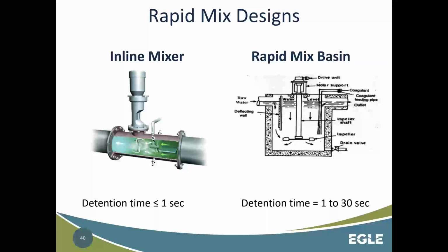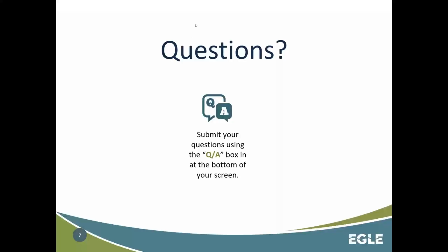Just want to repeat that when you get to flocculation, you're looking at gentle mixing. So we definitely don't want to mix the water rapidly to promote additional collisions. And then it looks like a few folks had adding additional coagulant. Typically, that's not a part of the flocculation process. So maybe just a little mixed up. Again, the terminology is important and they kind of blend together, but especially for the sake of taking exams and things, it's important to make sure that you have the terminology correct.